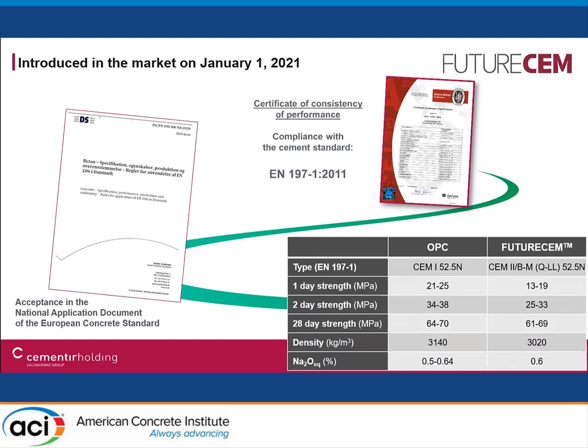And what you can see, it's really like a high strength OPC type. The 1 day strength is a little bit lower, which is fairly normal for a pozzolanic cement compared to an OPC, but the 28 day strength is actually the same.